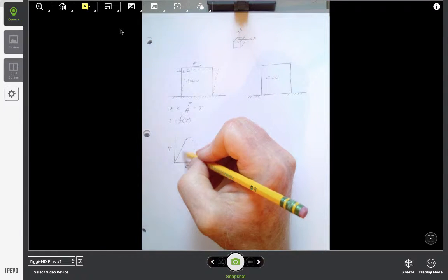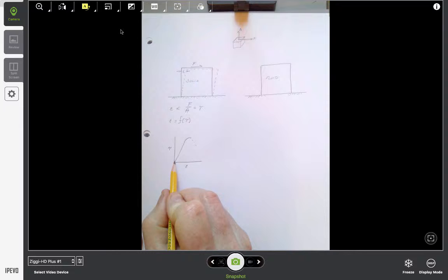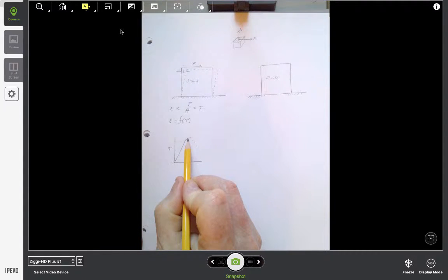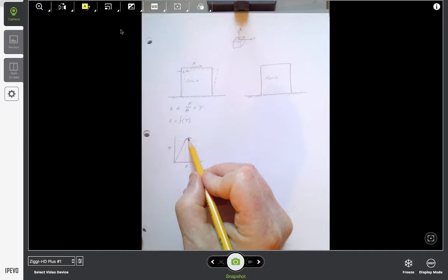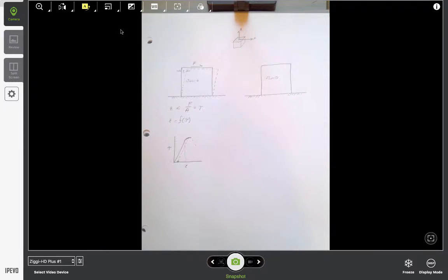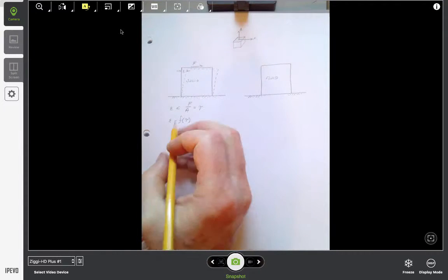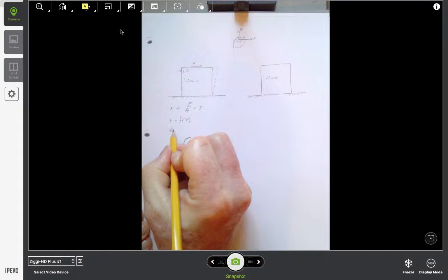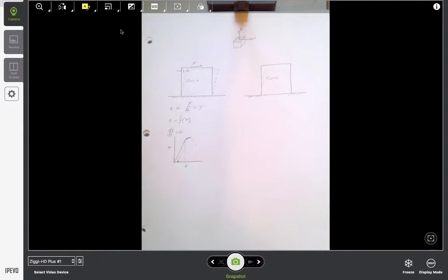Back in your materials class, you would apply, I'm plotting stress and strain this way, and that may be opposite to what you're accustomed to. But in this range, when the stress is removed, the strain will go back to original conditions. If we go out too far, if we overstress it, when it comes back, it will have a permanent deformation. Okay, that's a solid. The other important thing is that the change in strain with respect to time is equal to 0. Once it reaches its new equilibrium, it stops moving.